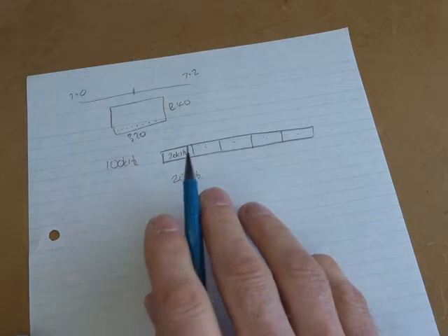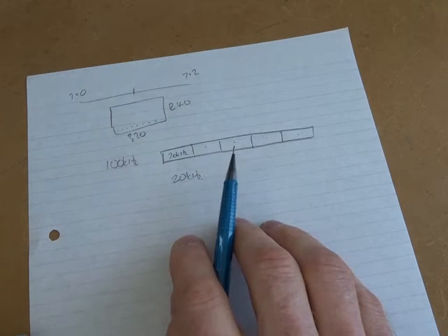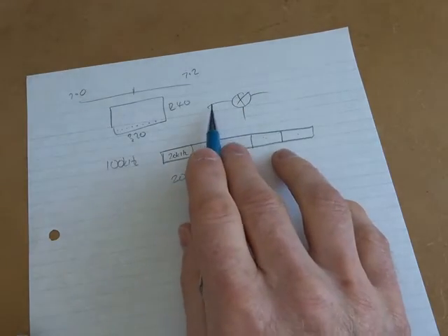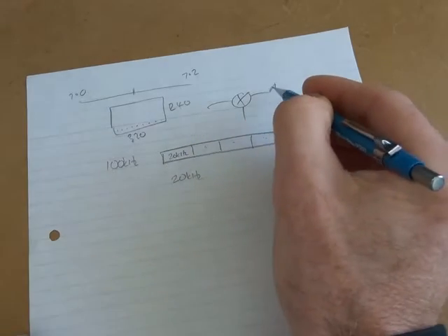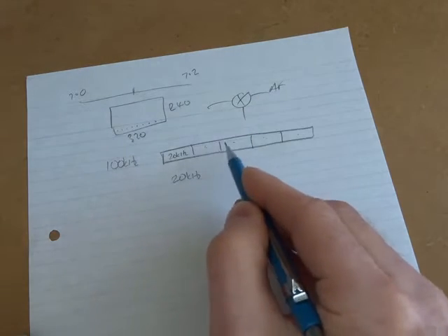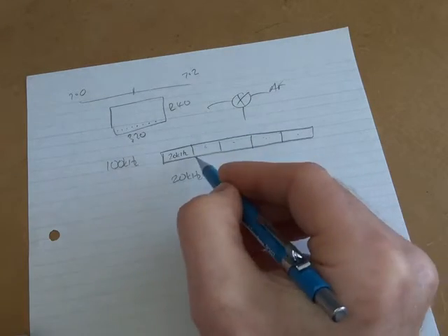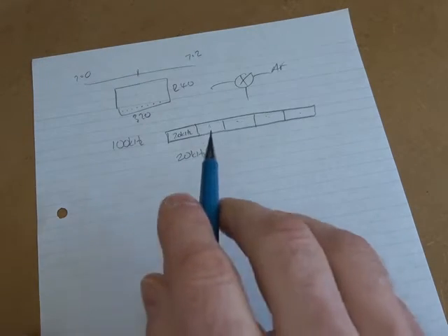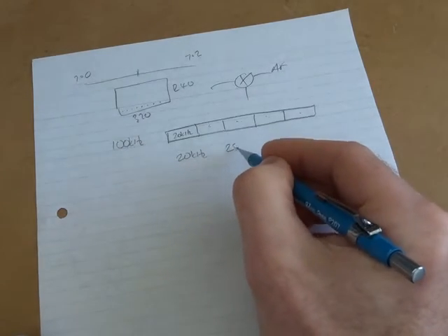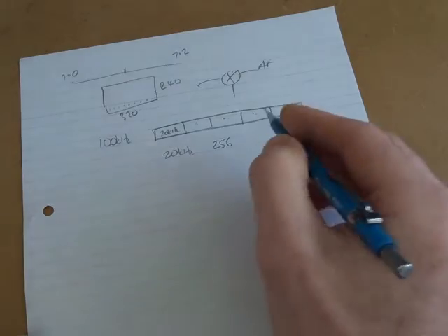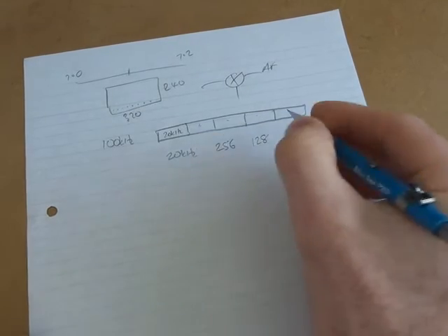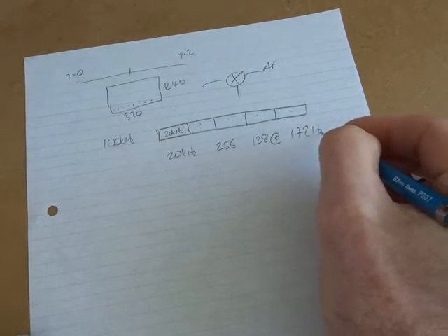So that would be using that Si5351, using that spare clock to mix our IF down into AF, and do that at 5 different frequencies to then produce these 5 little mini bands, so to speak. So using the 256 point FFT, that gives me 128 bins per analysis at 172 hertz per bin.